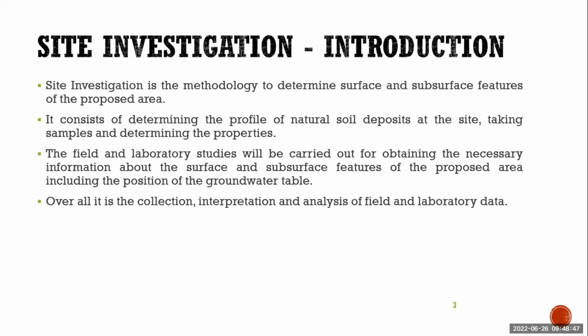What is native soil? Normally we know that whatever soil we see, all of it originated from rock. The rock slowly becomes soil, in simple terms. If it is not disturbed, then the rock itself is converted into soil. If we get that kind of soil in the project site, that is called native soil. In other terms, we can call it residual soil. Why do we call it residual soil? We can see the remnants of that rock. In general, residual soil is much better for construction.